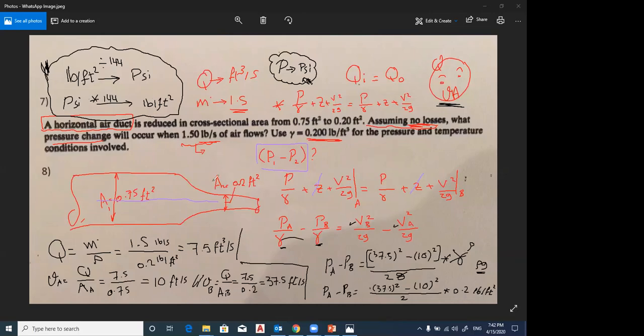On the other hand, if the required pressure we get in pound per feet square but the choice is normally in PSI, just divide pound per feet square by 144 to convert to PSI. Is this clear?